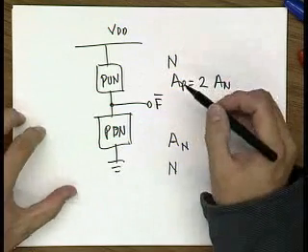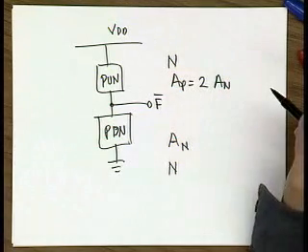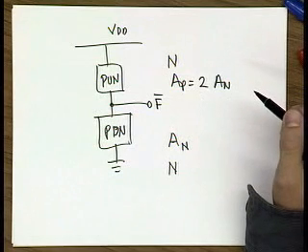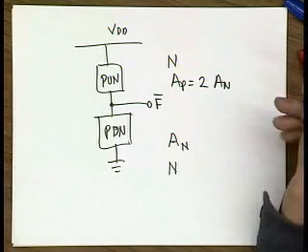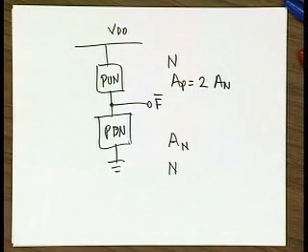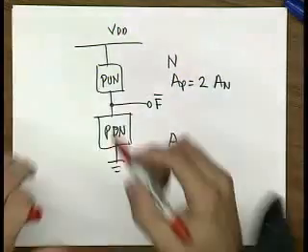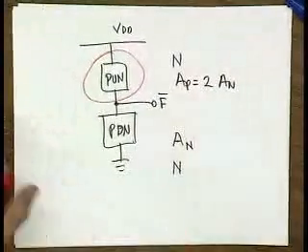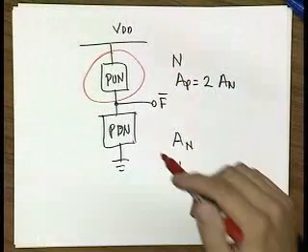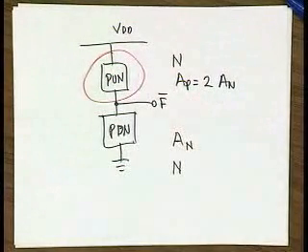So basically you have A, overhead in the number of transistors, and B, overhead in overall area that is required for the implementation. So for this reason, people started to look into alternative logic styles and say, well, this pull-up network, I don't really like it, because it's very area consuming, and all it does basically is implement the same function as the pull-down network.